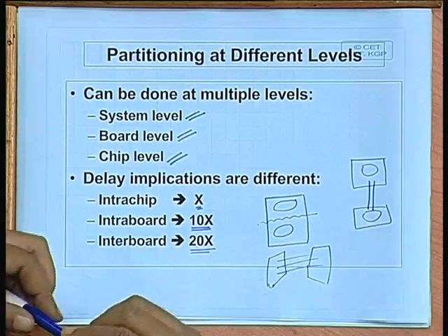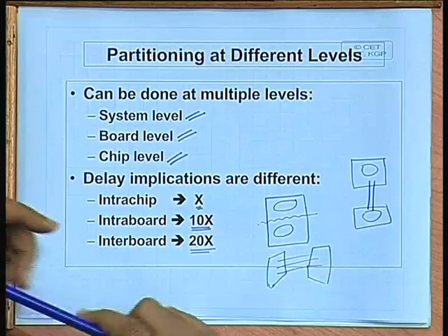So, this delay is delay in the circuit? Delay in the circuit. There will be capacitive loads and other loads when you are driving off chip. Off chip delays will be much more due to that, because the capacitive and the resistive load will be much more when you are driving some signal outside the chip, as compared to inside the chip.